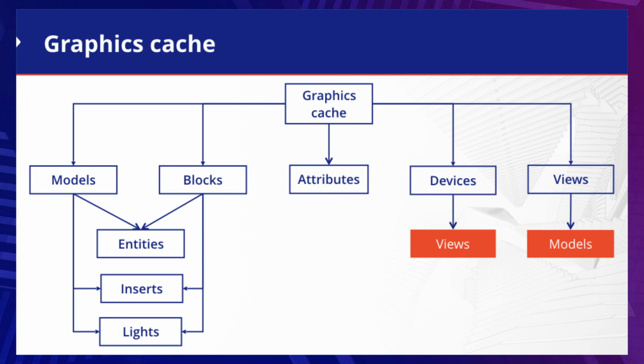And the last two types, devices and views. Devices usually encapsulate the graphical user interface window and own, update, and generate the views. Views usually store the parameters of the camera and many other properties. To draw something with Visualize SDK, first of all, create the device, create the view, and append this view to the device, create a model, fill this model with the geometry, and append the model to the view.